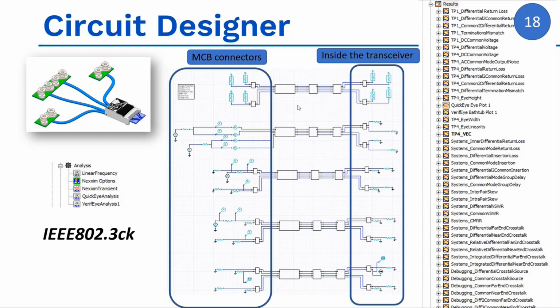So in my case, you see, I plugged my three parts in series. In your case, you can remove these ones and put your own. You can also add the ASIC part. I don't have any ASIC part. I'm assuming that my ASIC part, which is inside the transceiver, is a perfect 100 ohm termination, which we know is not true. To have more accurate results, you need to add the ASIC. So it's a standard way of building models, preparing them to be solved, and uploading the right solver. And in the solver, of course, you have to set the same frequency as within your HFSS model.